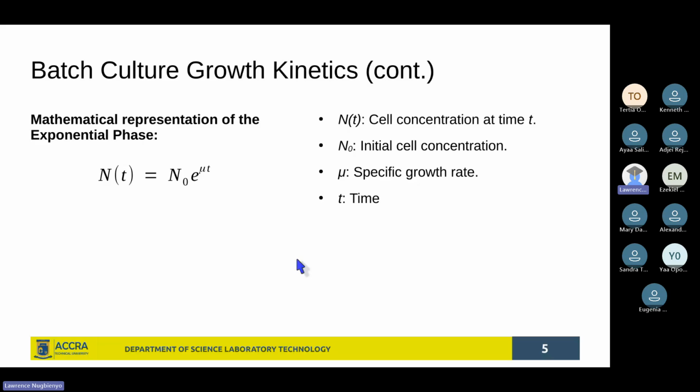So you do not have, say, the last end, which is the cell death, getting so deep into the process and contaminating your product, because then you start to have toxic metabolites that are being produced by these microorganisms together with the cells that are dying, and toxic conditions are then created in there.